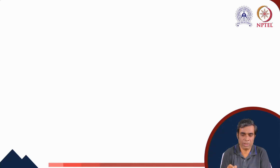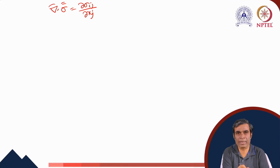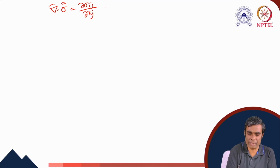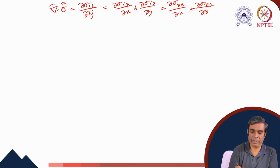Now this divergence of sigma I have shown in the previous class. So this is the vector. It is del sigma ij, del xj, and I have already told you that the momentum equation is a vector equation. So i is the free index and j is the repeated index. So easily we can expand this term. This will be del sigma ix del x plus del sigma iy del y in 2 dimensions. So we can even write it, for the x momentum equation, as del sigma xx del x plus del sigma xy del y.